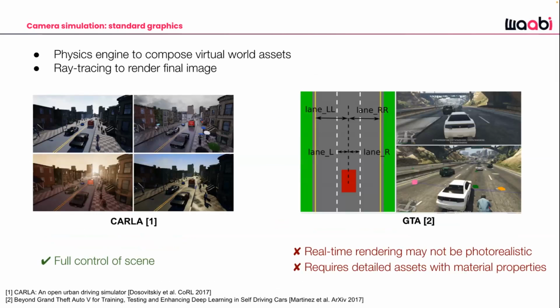Now that's talking about the subcomponents for camera sim. I'll now talk about the full system camera simulation approaches. There are game engine-based approaches such as, say, CARLA, or Grand Theft Auto, for camera simulation. You have full scene controllability, but the downside is the domain gap, because there's a gap between simulated sensor data and real data, especially if you're trying to run your sensor simulation fast.